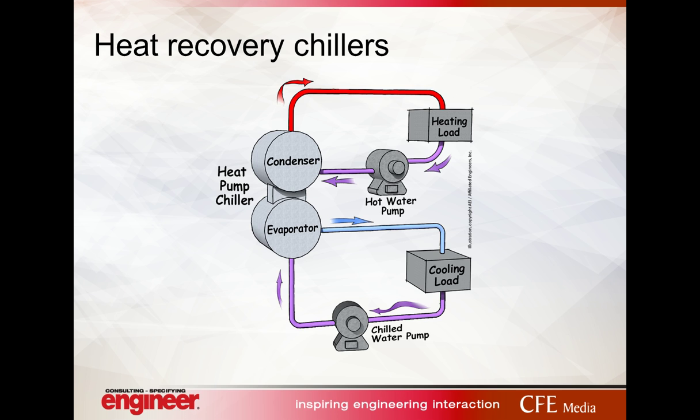Heat recovery chillers have a lot of synergy with hospitals. We've already mentioned the term simultaneous heating and cooling several times. It's almost unavoidable in a hospital because you have code minimum air change rates that may be different than what it actually takes to heat and cool a building. So there will still be plenty of times during the seasons where you're going to have simultaneous heating and cooling.